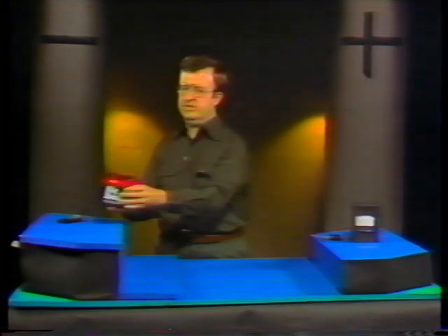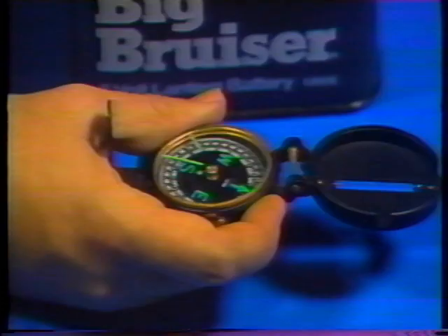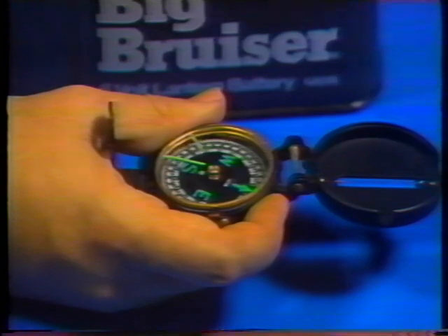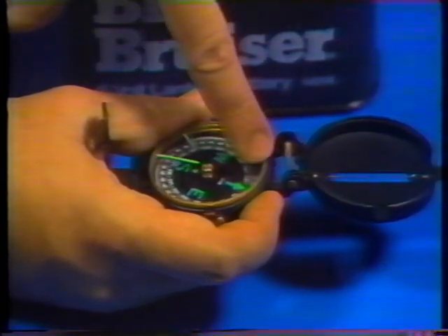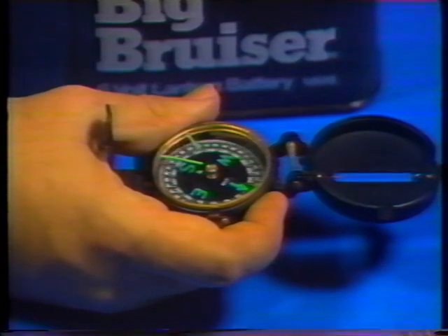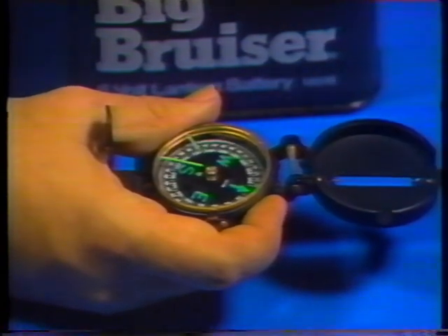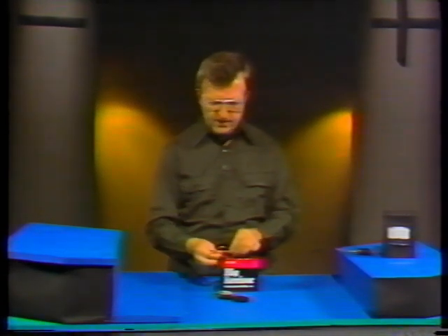Okay, we've seen that a magnetic field, together with mechanical energy, can produce a voltage. Now, let's see if current flowing through a wire can create a magnetic field. To find out, we're going to need a circuit and a compass. Now, this needle is pointing toward north because of the Earth's magnetic field, right? And it will continue to indicate north unless it comes in contact with a stronger magnetic field. Well, if what I said about current flowing through a wire causing a magnetic field is true, then we've got a magnetic field right here as soon as I close this circuit.